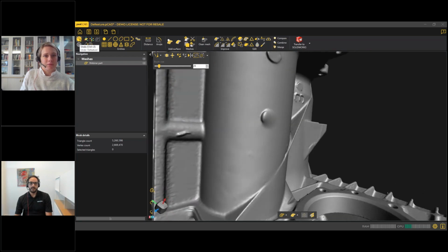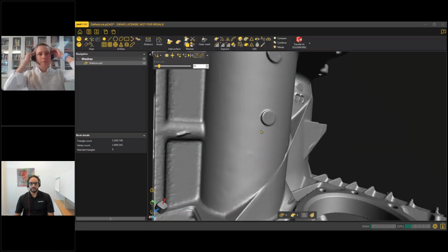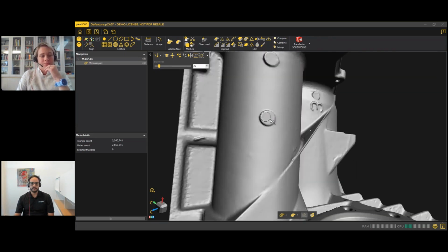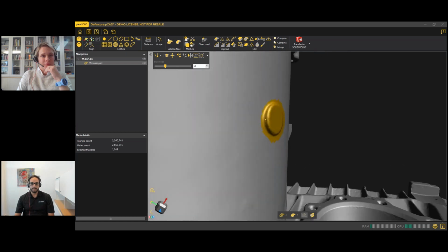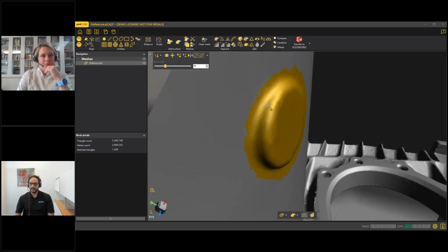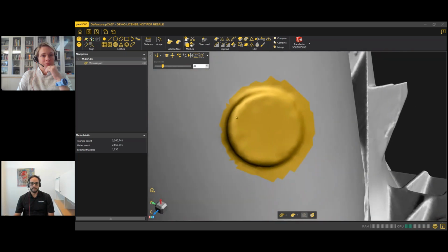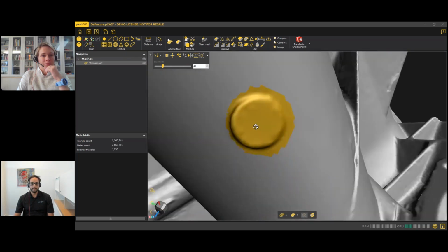So I will go back here and, at this time, I will make sure I have all the surface selected. So make sure we have no undercuts on it. And so we will select here again, another selection. Make sure I have everything selected here. So even a small triangle like this here could be a problem. So make sure I have nothing left on the selection.